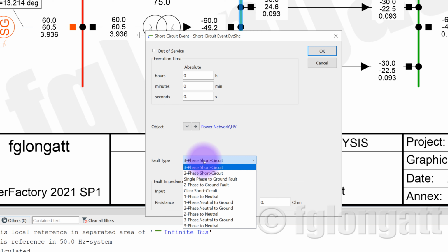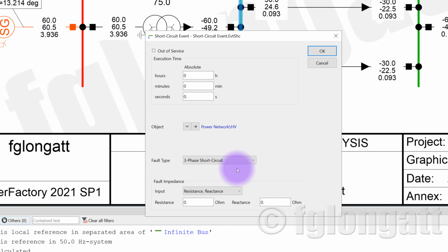Okay. However, remember the following. We are running a positive sequence simulation. And because we are running a positive sequence simulation, in this case, the only option is 3-phase short circuits. Because 3-phase short circuits are symmetrical faults. You must remember that from your previous course. And 3-phase faults are symmetrical and balanced. Okay. That means we are right. Let's keep the selection, 3-phase.